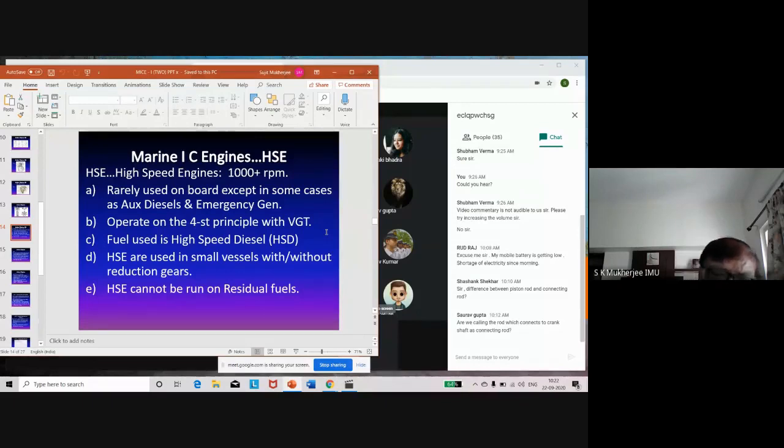Okay. Now, when you start the engine, there is hardly any exhaust gas. All right. So with hardly any exhaust gas, the turbine will not pick up any speed, or it will take some time to pick up speed. And during that time, there will be hardly any air supply to the engine. If there is a shortage of air supply, the combustion will not be satisfactory. So part of the fuel will burn, part of the fuel will not burn. It is only when the turbine can deliver more air through the blower that the engine will pick up speed. Isn't it? You can give more fuel, but that's no good unless you give more air.